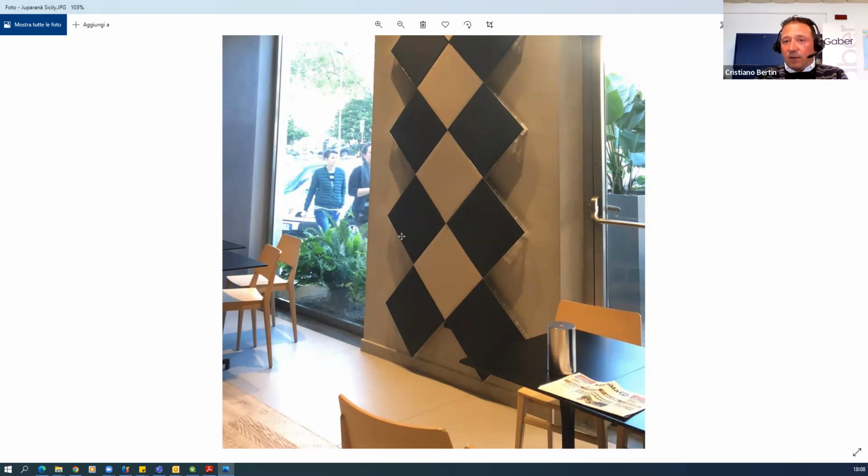First of all, the fabric should always be an open cell fabric, and then should have a part of plastic, polyamide or polyester. Otherwise, it does not work on molding. It doesn't mold, we're not able to shape. And of course, open cells, why? Because if it is closed cells, it does not absorb noise.